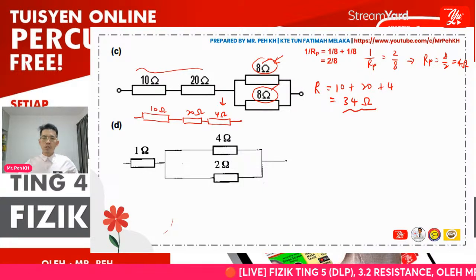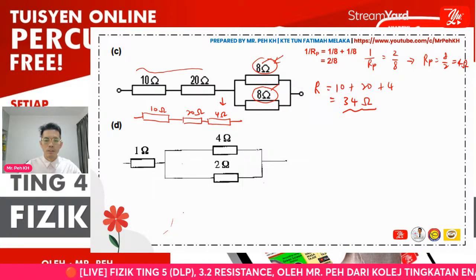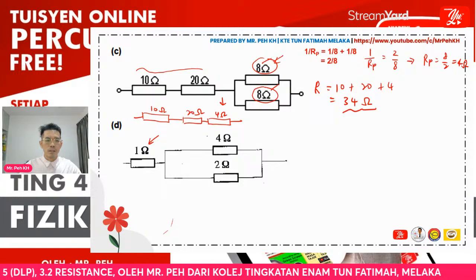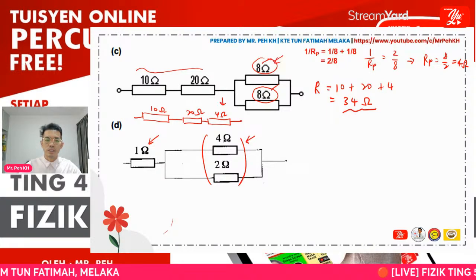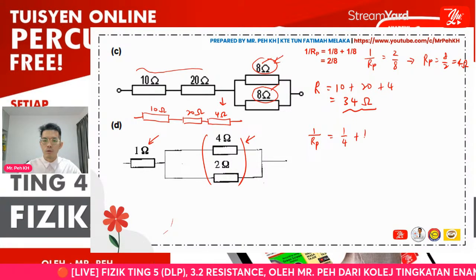Then the next one here, there will be series, and here will be parallel. So again, we have to solve the parallel first for this question. 1 over RP equals 1/4 plus 1/2.